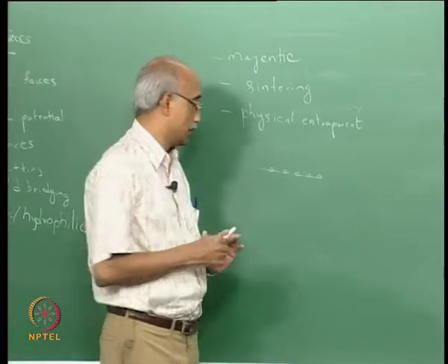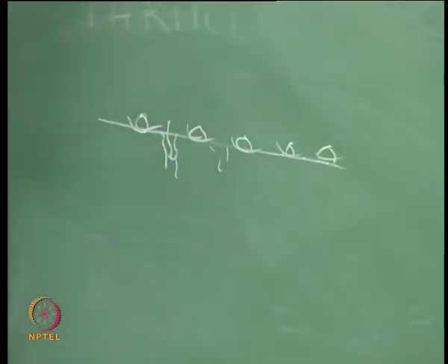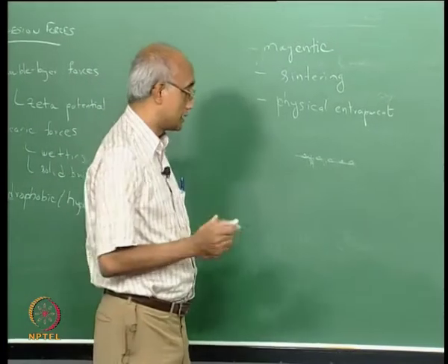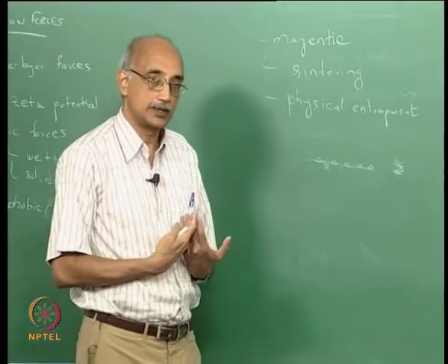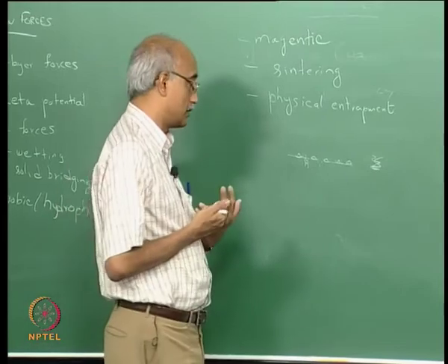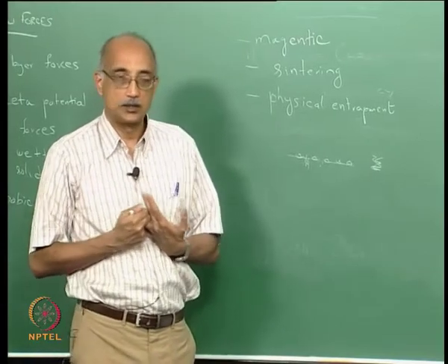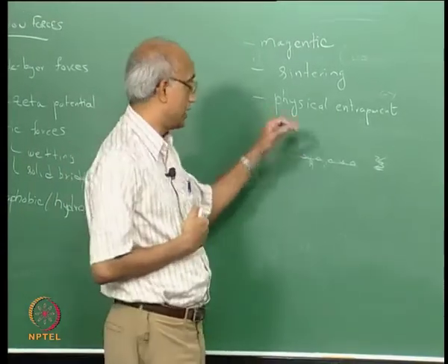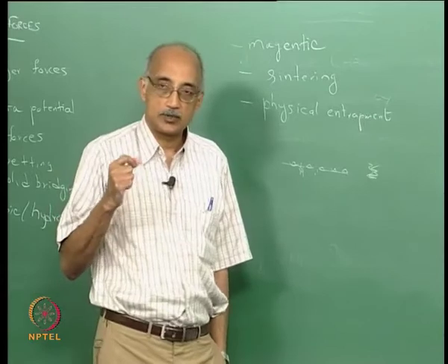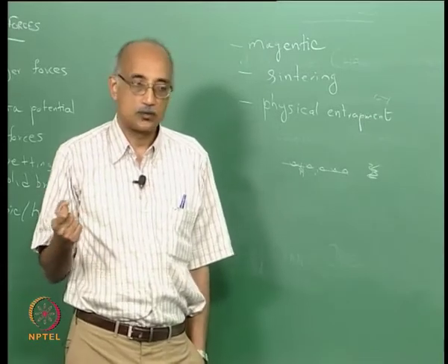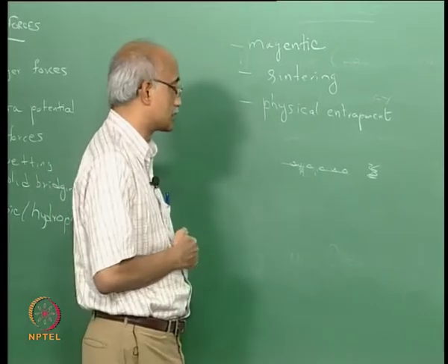Another example would be porosities that particles can diffuse into and get captured. Another example would be matched roughness elements. If two surfaces are brought together in such a way that their roughness asperities interlock them together, that would be another physical entrapment. These are examples of forces that are somewhat unique to the application, but which provide adhesion forces that are far in excess of the forces that would apply otherwise in the absence of these features.